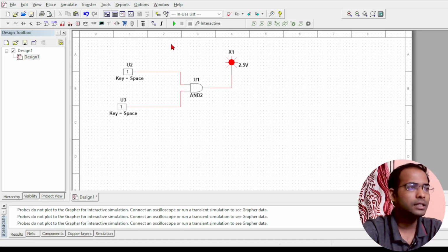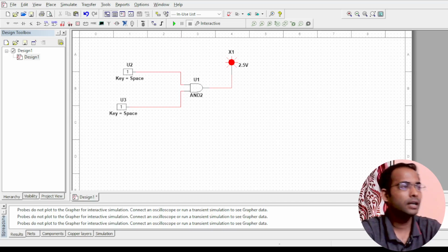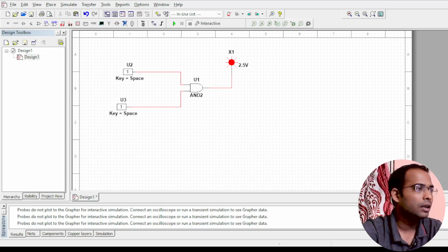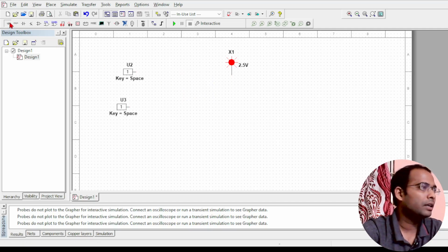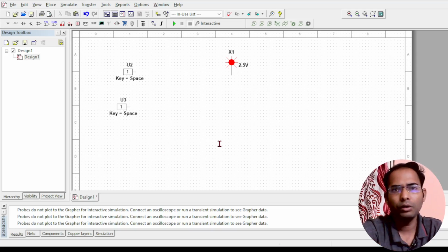The same thing we can see with the 7408 IC also. So this is the IC number. You can take a snapshot of that. You can try with that. So let us do it with the 7408 IC here. So this I will just remove, and from here I'll try to find the 7408 IC. Where do I find it? I'll go to TTL logic here, from the 74 series. 7408 is there. It's a quad 2 input AND gate.